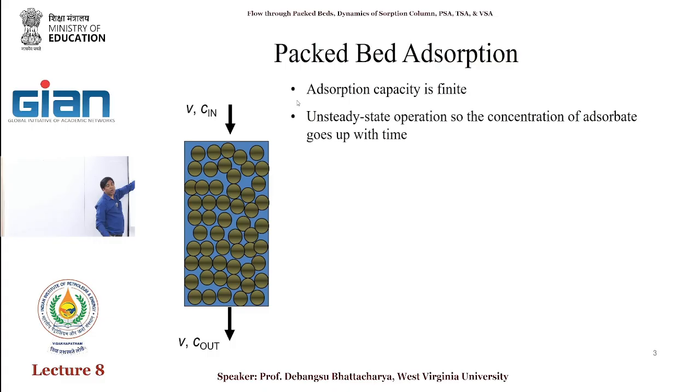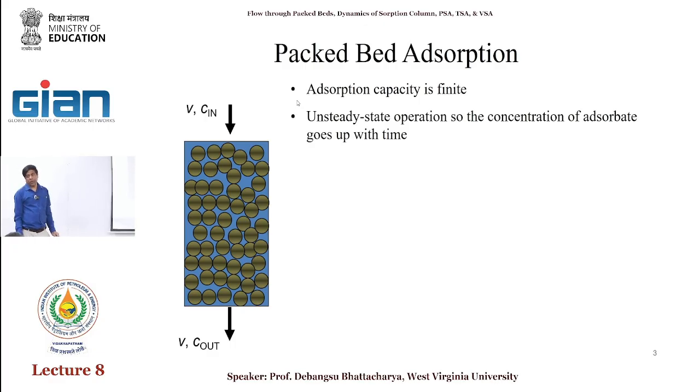Then the gas over here will have higher CO2 concentration, and then they will take their turn, and they will take their turn. These guys at the end may never take their turn. It really depends upon their mass transfer resistances and other kinetics. So a portion of the bed may really do nothing and it has already broken through. And that's really the thing that you have to think about. So the question that comes up is, from a design perspective, instead of arranging it this way, would I have arranged it in some other way?